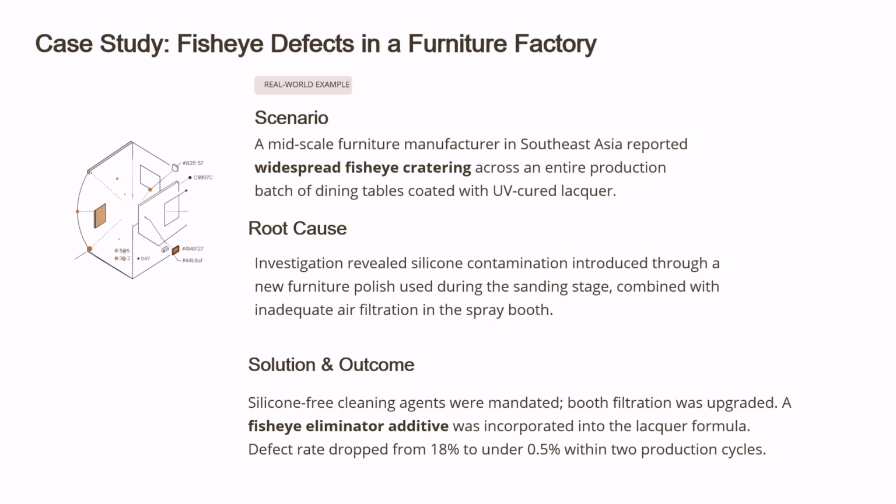To solve the issue, the company switched to silicone-free cleaning agents, upgraded the filtration system, and added a fisheye eliminator to the lacquer. As a result, the defect rate was reduced significantly from 18% to less than 0.5% within 2 production cycles.